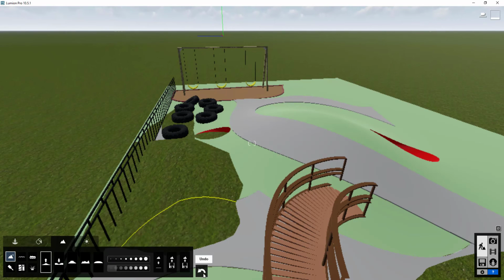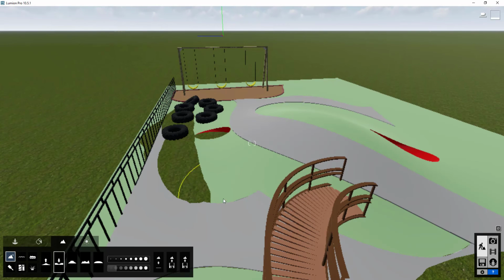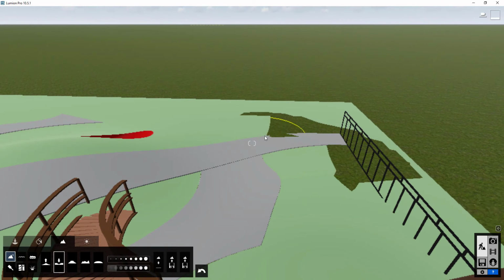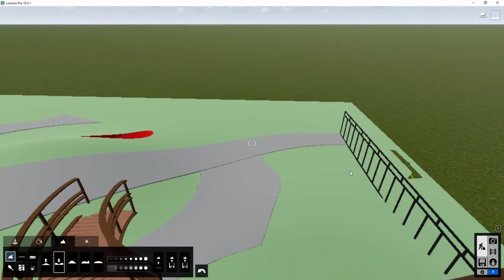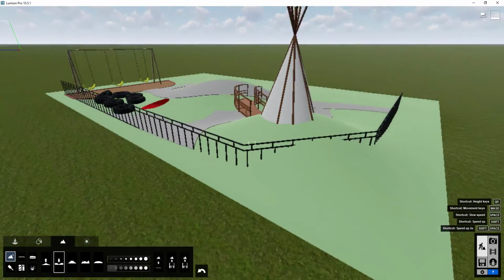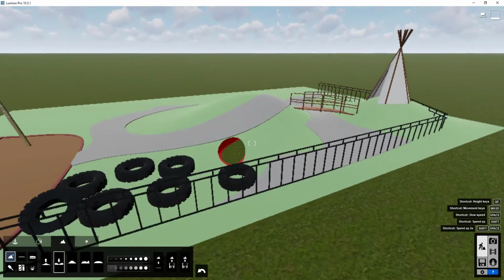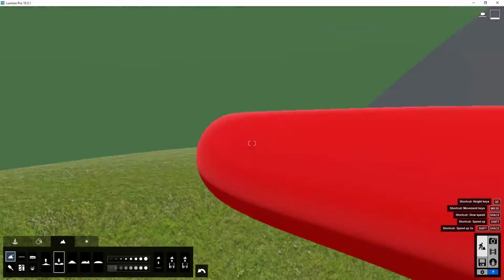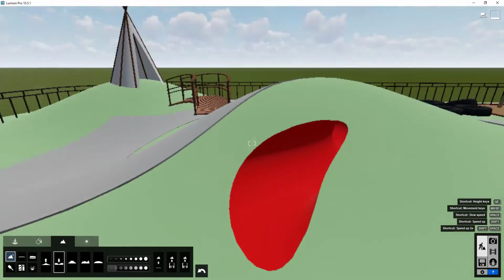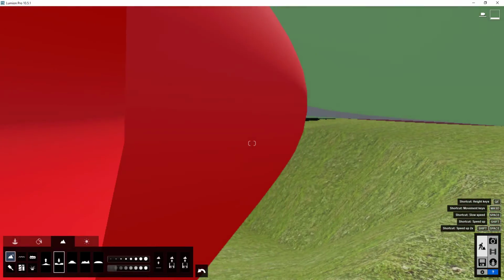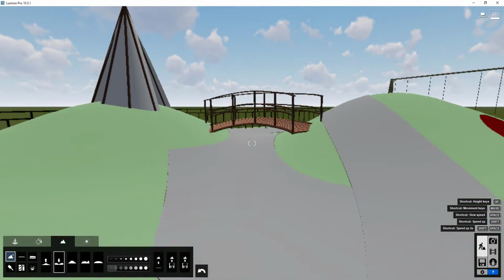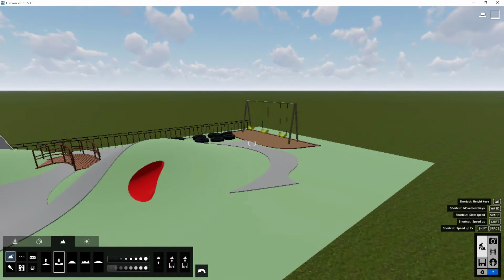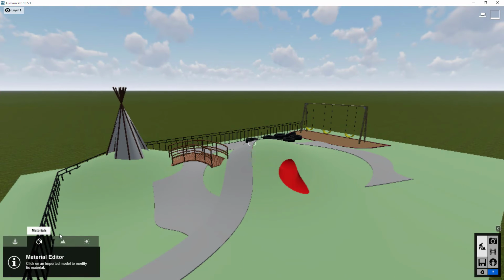Oops, it's the other way around. Undo and lower, just like that. That works nicely. And now all you have to do is assign materials and work with the base files. Be very thorough with your model and be sure of any intersection with the ground plane. And now if you have everything alright, all you have to do is just assign different materials in different objects.